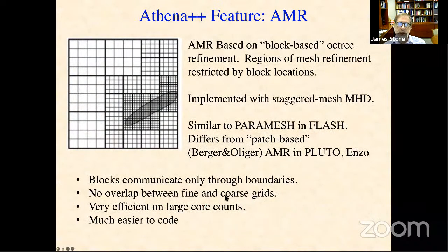So the important ingredient of this is adaptive mesh refinement. For those who are not working in computational fluid dynamics, let me just explain quickly what that is. Basically, your computational domain is broken up into blocks. Here, this domain is broken up into 3 by 3 blocks. It's a two-dimensional domain. And if there's some region of space where you would like to resolve it better with smaller cells, finer resolution, then you just divide the blocks into smaller blocks and keep subdividing those smaller blocks into yet smaller blocks.